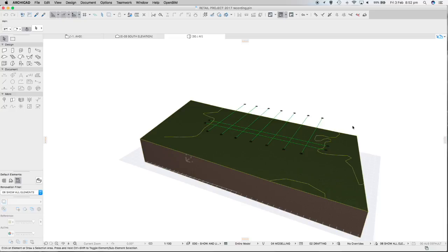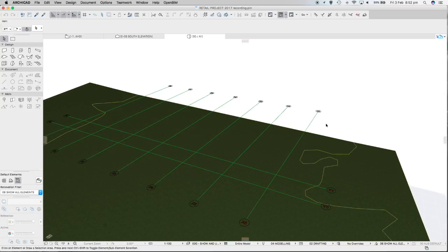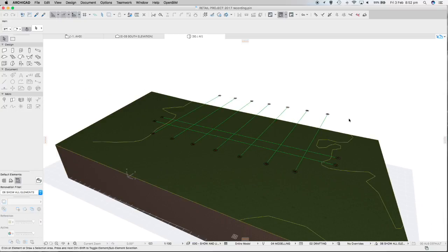We'll use Archicad's solid element operators to do this. Basically, we're going to create some other solid elements, the shape of the cuts we want to make, and we'll use those elements to subtract from this mesh or add to the mesh, as the case may be, for cut and fill. We will subtract for cut and we will add fill. Okay, that might not have explained it too well, but if we actually do it, that'll probably help the explanation.